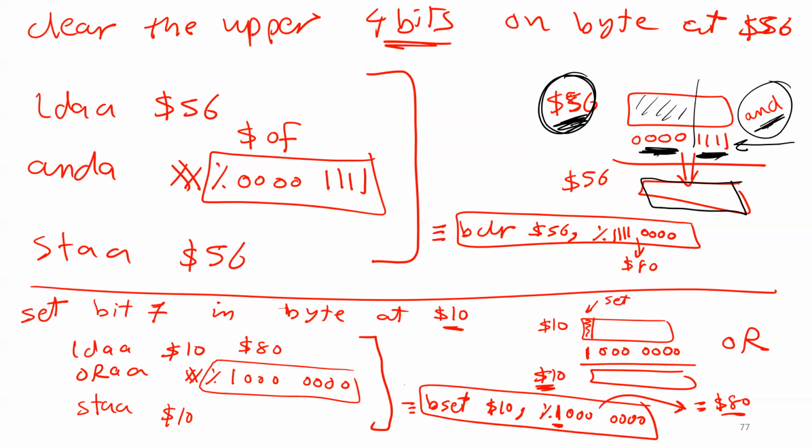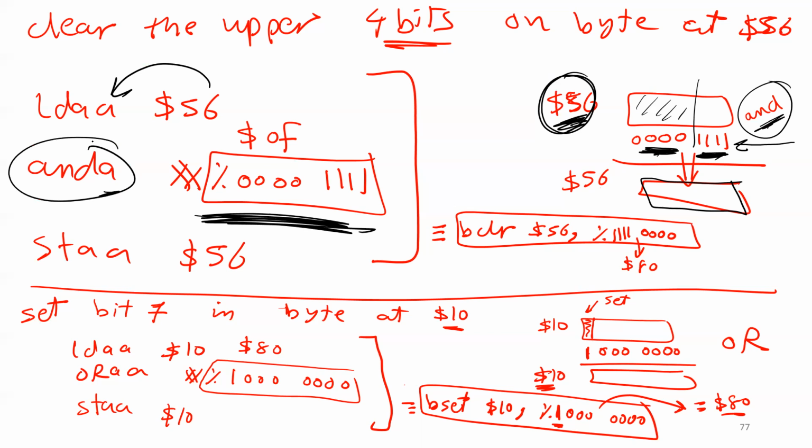It has to be done through register A, right? That's exactly what I did. Look here, guys. Number 1, I'm gonna read the byte as you see here at location 56. Number 2, I'm gonna do AND with this number, 000111 this way. Is that okay? And then the result is in A, so I have to return the result back to 56.